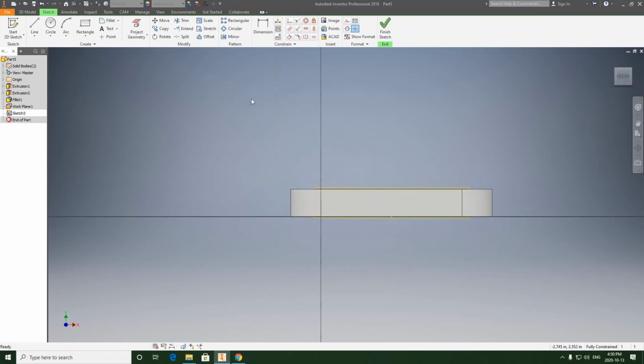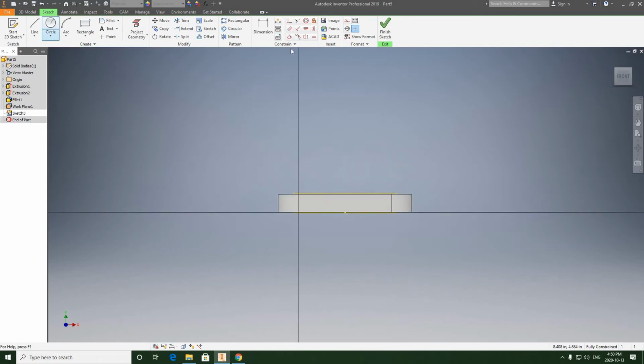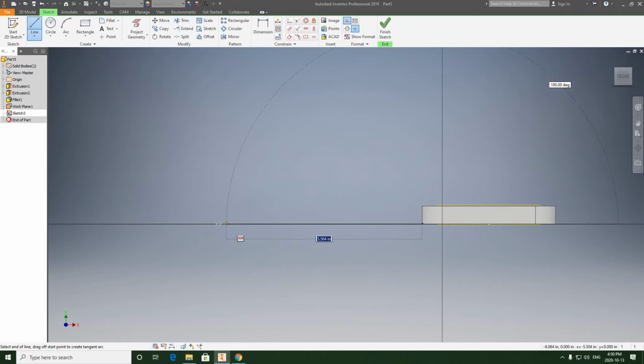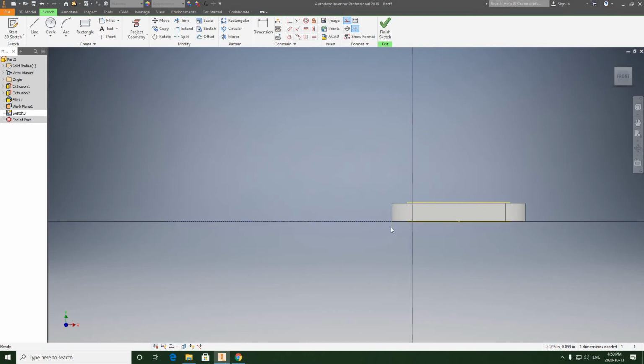And we're going to draw some construction lines. To grab a construction line, it's on format, so where it says construction, I'm going to push that, grab my line, and come down to this endpoint and draw a line horizontally from the bottom. It doesn't really matter how long it is. But it should be purple because it's constrained already to this point at the bottom.